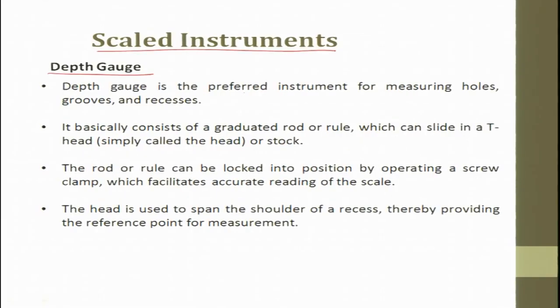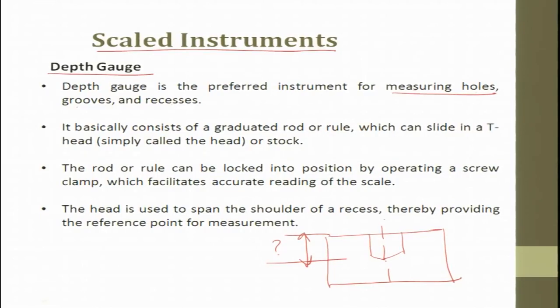The depth gauge is the preferred instrument for measuring holes, grooves and recesses. Suppose you have a blind hole and you want to measure its depth; the depth gauge is the only possibility which can be used. You can also have through holes, grooves and recesses, so we use the depth gauge.